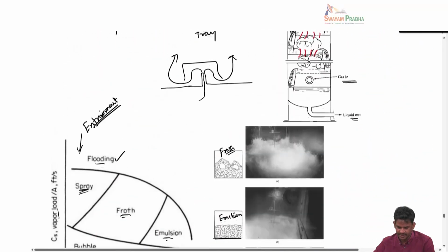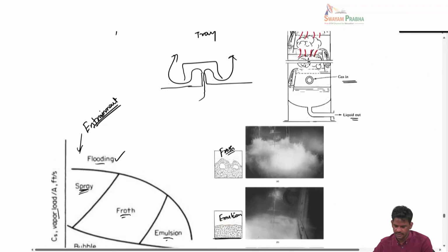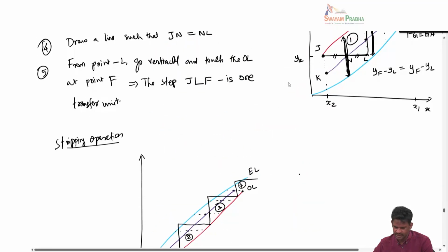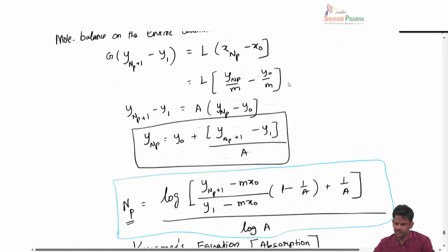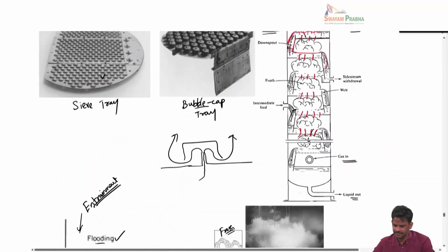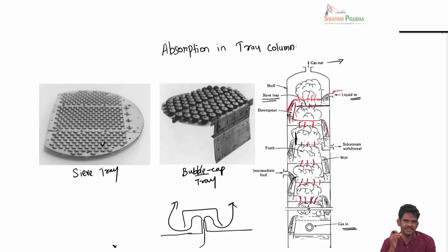if I go back to the design, see there is, yeah, here. This picture is not very neat, I think. Let us see. Yeah, this is the best one. If you look at this particular design, there is a small weir here, a liquid leveler. If I increase this, I can increase the level height. So, it is a design parameter. When you design your tray, you can design it in such a way that the liquid column height can be increased. But if you increase the liquid column, the pressure drop also will go up. So, these are the compromises we have to make.